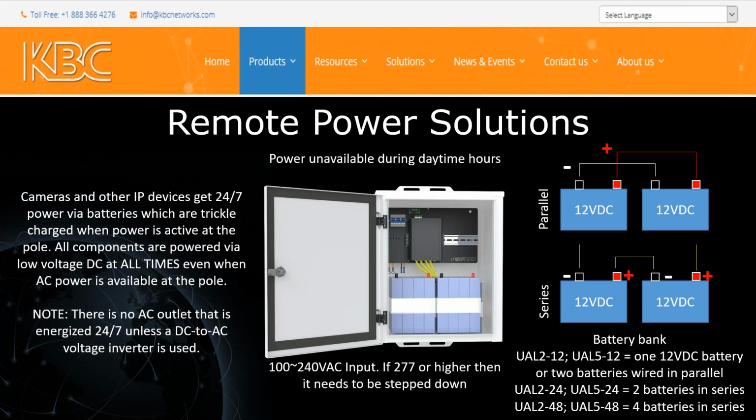And so you have this AC to DC just back and forth, and that creates power inefficiency. And it's important, especially with a battery backup system, that you keep the power as efficient as possible. So when we build these systems, or when we build your spec and your design, we are trying very hard to avoid the need to go back and forth from AC to DC.